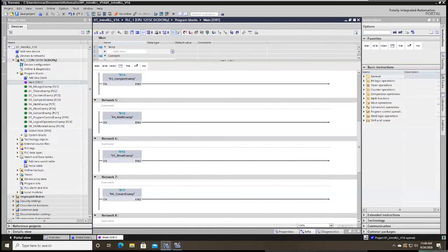That's the only way I can think of doing it. But like I said, I know I have a project somewhere that does, I think, exactly what you're looking at. I have to dig it up. It would require you to download to the PLC, which is the only downfall. If it's something that's currently running, you might not want to download. It's a software change, but either way, I think you'd have to simulate it using a subroutine, to say the least.